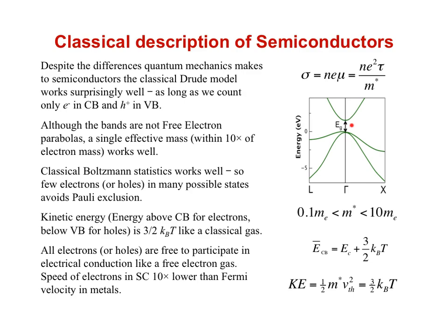When the Fermi level is within the band gap, there are so few electrons just at the bottom of the conduction band and so few holes just at the top of the valence band that classical Boltzmann statistics works quite well. This is because there are many more possible electronic states than available electrons or holes, so that the Pauli exclusion principle has little effect.